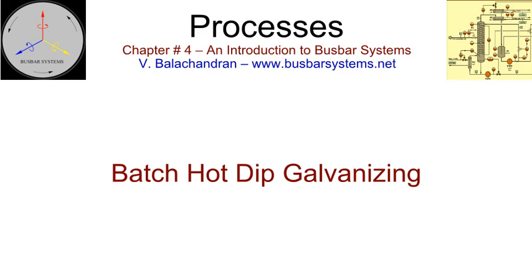This industry has been dictated mostly by the requirements of transmission and telecommunication towers, steel bridges, lighting masts, and similar structures. In this case, most of the members are long and the bath should be capable of accommodating such long members. Consequently, the capacity of the galvanizing shop is determined by the length of the member it can galvanize in a single dip. Some industries adopt a double dip to cater to the requirements of the sections that are longer than the bath. Double dipping can also be resorted to when the width of the component is marginally less than twice the height of the bath.